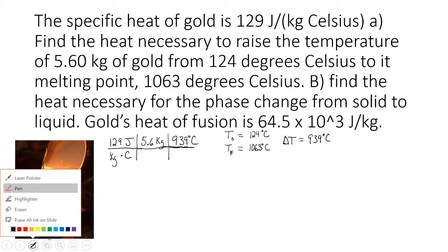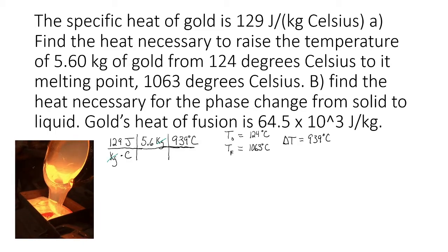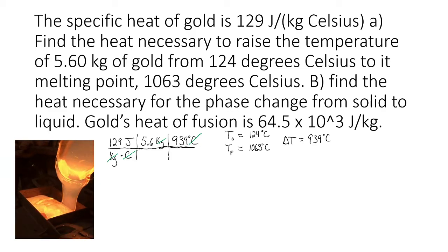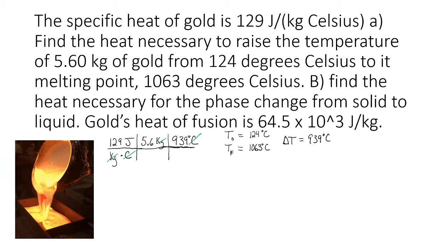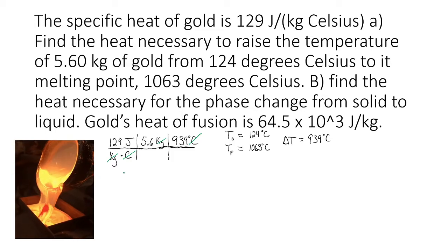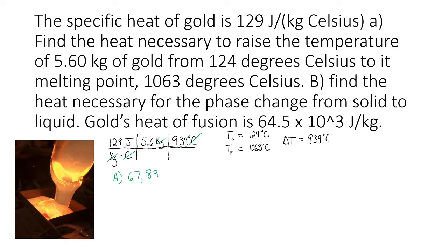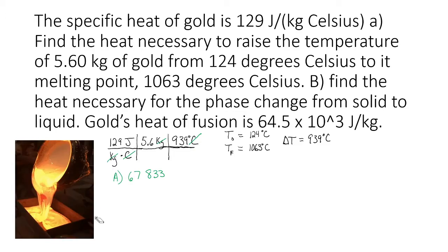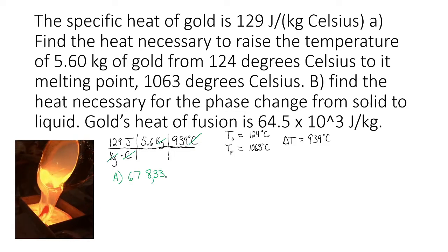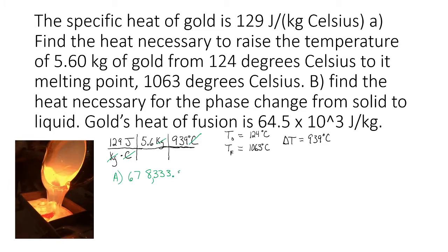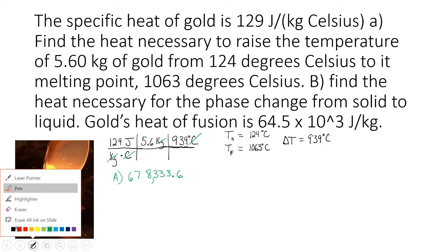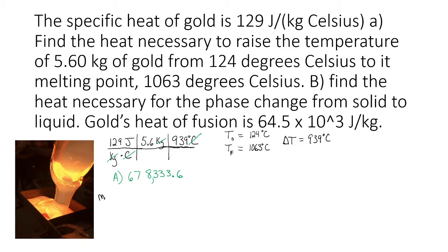At this point, you can see that the kilograms cancel and the degrees Celsius cancel. So it's 129 times 5.6 times 939. We get a grand total of energy that it takes to raise the temperature of that, 67,836. Oh, excuse me, just a moment. I read my calculator wrong. 678,333.6 joules.